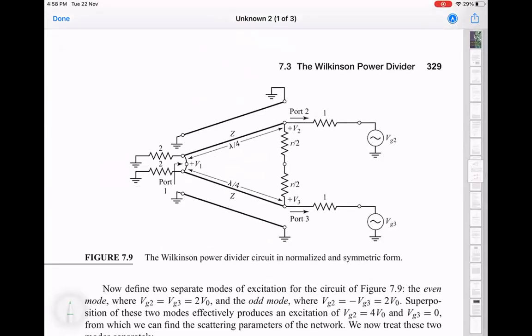One other reason for looking at this analysis is that it introduces this technique of even odd mode analysis, which is quite useful in general to handle complicated circuits, because you can simplify them under some special symmetry conditions. Okay. I think we briefly encountered this in some other example. I have this vague recollection, but I can't remember now. But it's for this slot line. No. When we were discussing coupled microstrip lines, right?